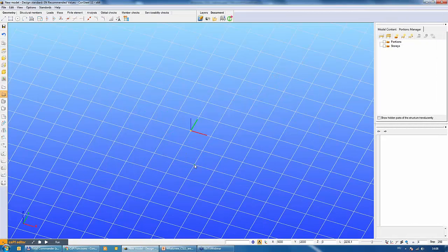Okay, so with the new csPI interface, parametric models can be built easily and run anytime. Any kind of ConSteel objects, such as members, plates, supports, loads, etc., and for loop and if-else statements can be used for parametric modeling. This is the first version of the csPI.